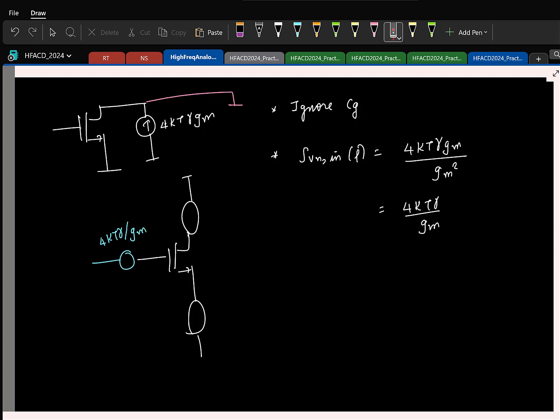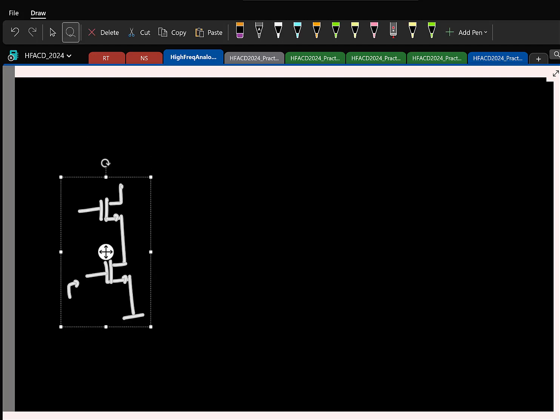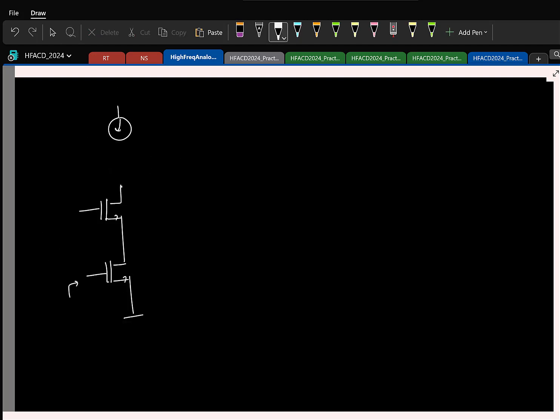Cool. So one more last circuit we'll do today. That will be our dear cascode. So in the cascode, here is where I apply the input, and let's assume that on the output side I have an ideal current source. Don't worry about what's here. Assume that this is an ideal current source. This is the output. This is incrementally short, or connected to a bias voltage.